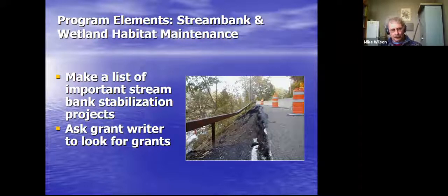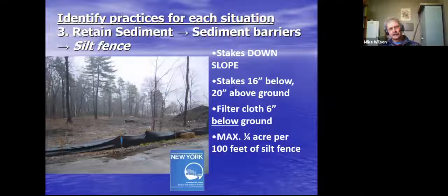What are your measurable goals? One of your goals is to make a list of the important streambank stabilization projects that need to be completed. One of the ways you can retain sediment is also with a sediment barrier like a silt fence. However, all too often we see these silt fences installed incorrectly. Let's make sure we do it correctly. Otherwise, it has absolutely no benefit whatsoever.